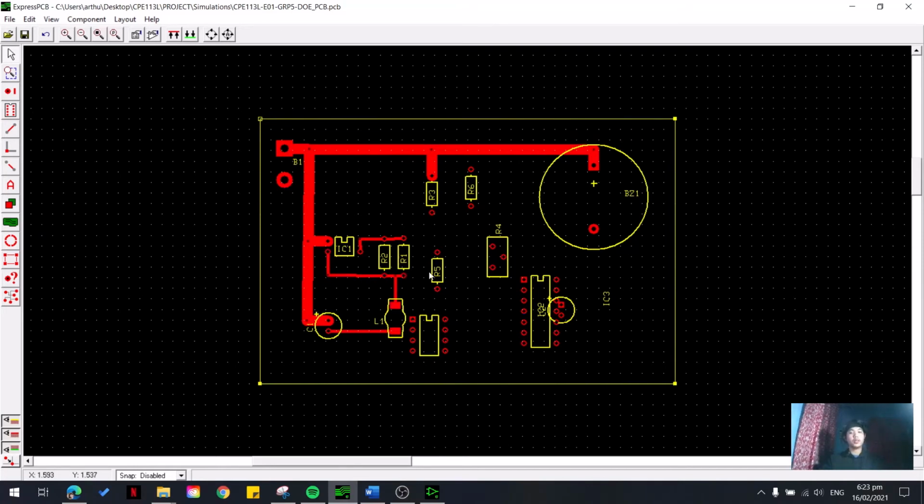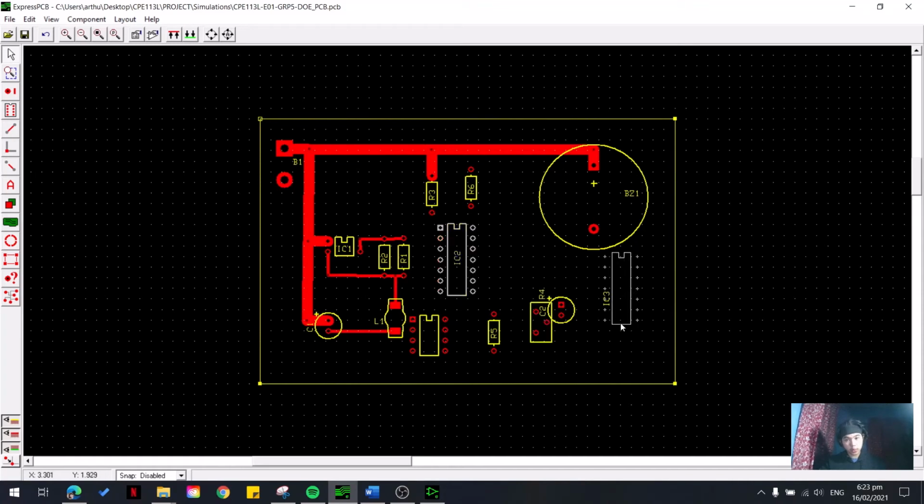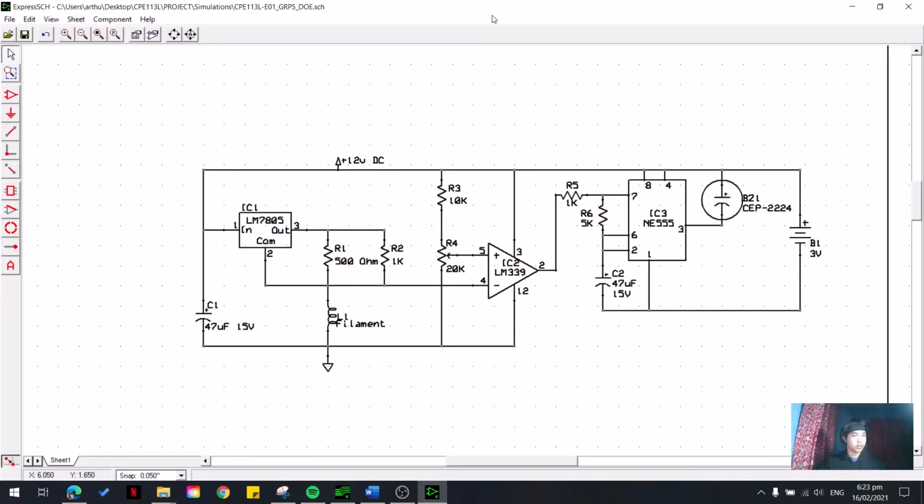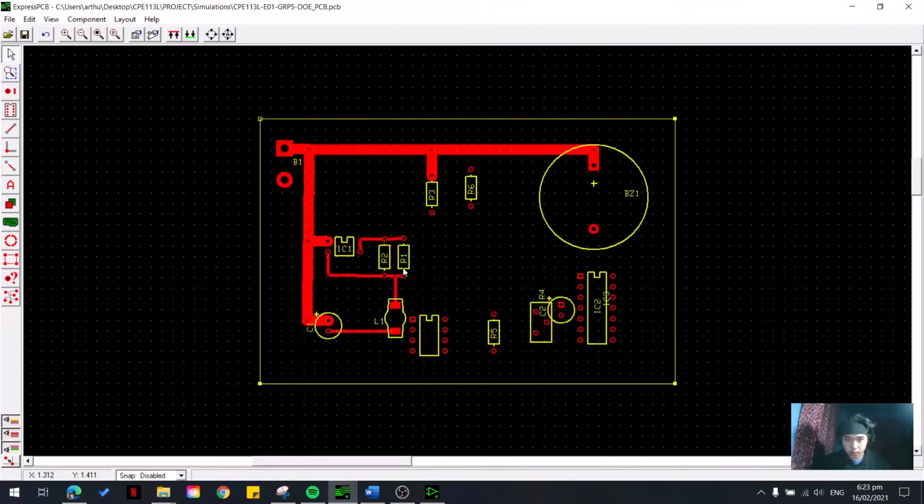So now we're going to connect them to IC2. So it's time for IC2, the biggest one. I mean R4 first. As you can see here, this is R4. It's connected. This arrow will be connected to the middle of the potentiometer. The R3 goes here. So first, let's just interchange this because R1 needs to be the one on the left.